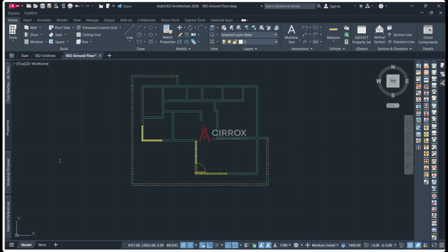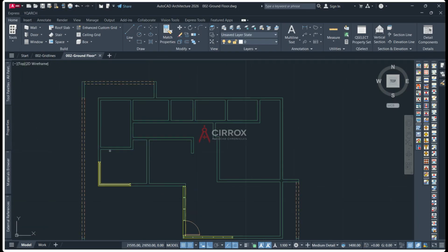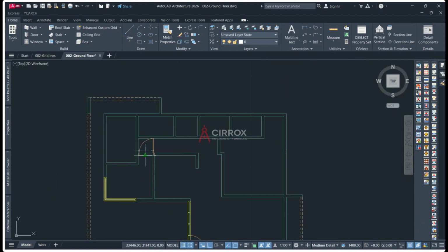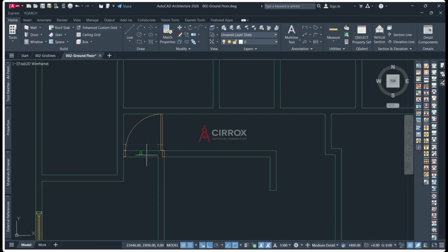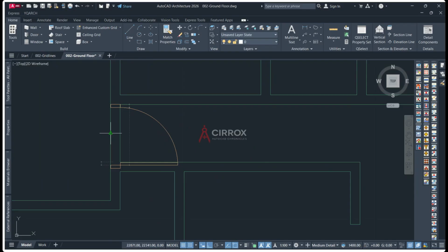or 238. So yeah, this is okay. So I can now fix in my doors. There's one door in here, so as you can see, I'm actually having a glitch in here. So now for me to fix it, I will now need to reduce the size of the door. So click on the door and reduce it to 800 or less.